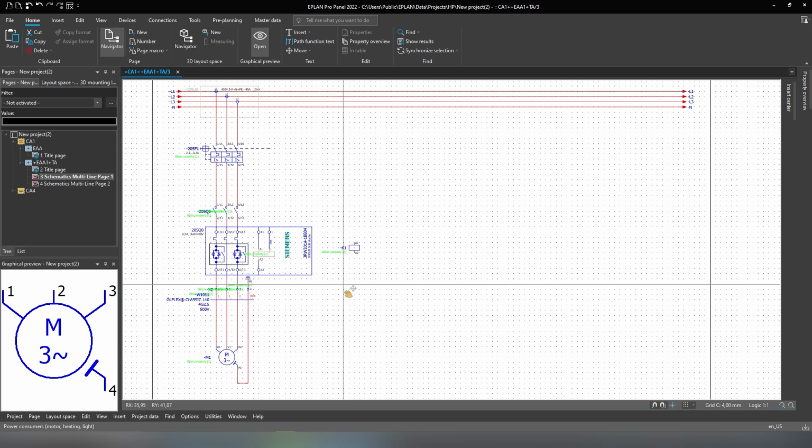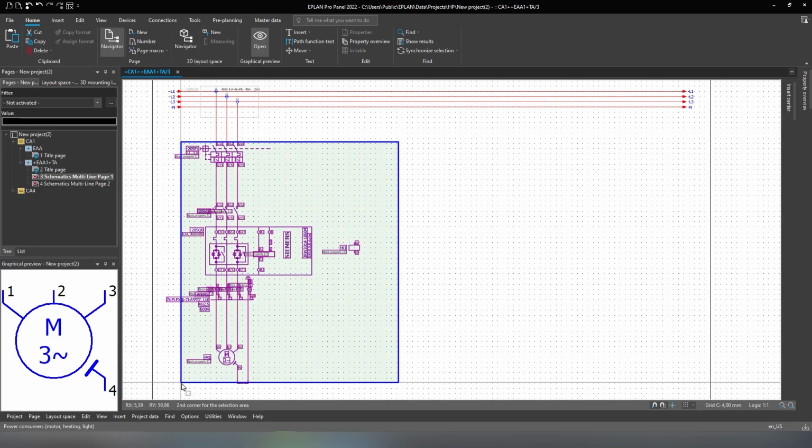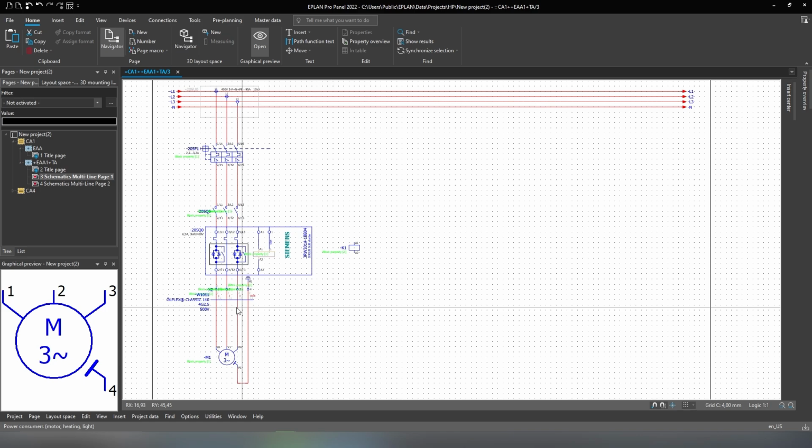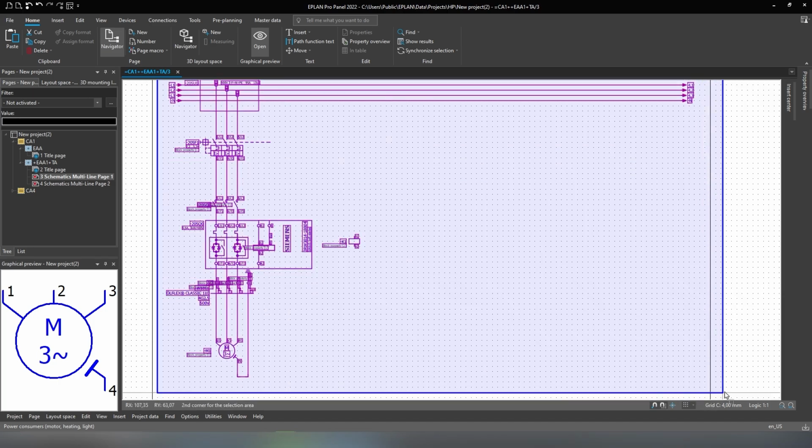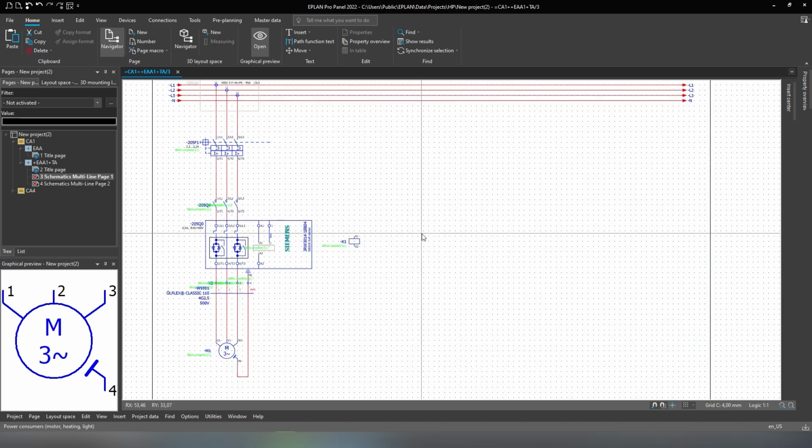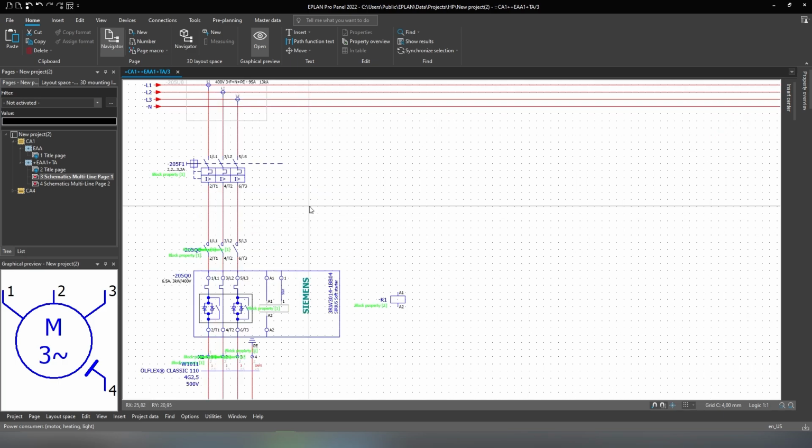So you would create a macros project, and then you would not have any articles or any parts behind the motors. You would create this type of page, and then in your schematics page, you just start pushing these pages that you have created into it. It's kind of like a copy and paste. But with the macros project, you don't just paste it 1,000 times. You just click that I want to have it 1,000 times.